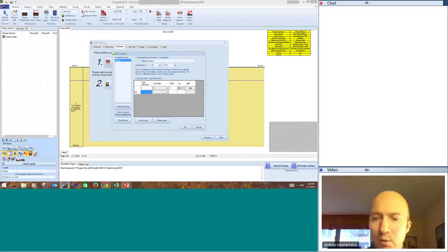So we're going to go at -10 elevation and apply a clay. In clays in our nonlinear modeling, it is important to specify the overconsolidation ratio because that controls your undrained shear strength.